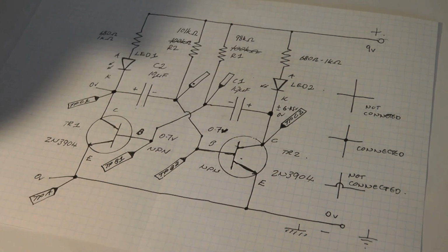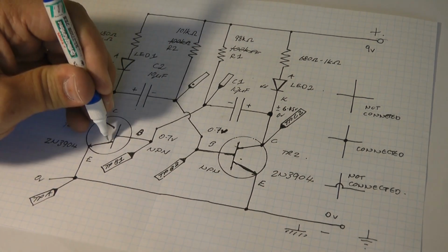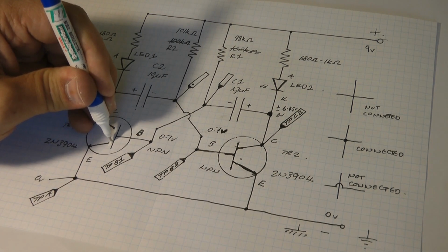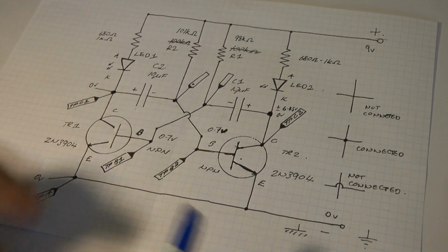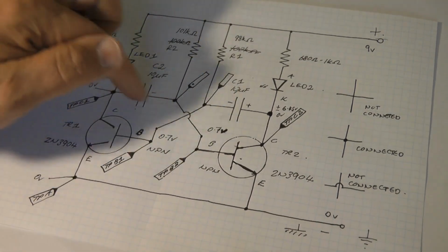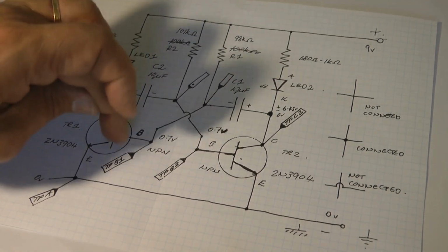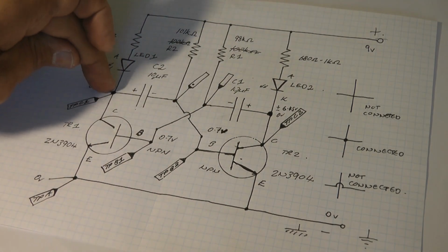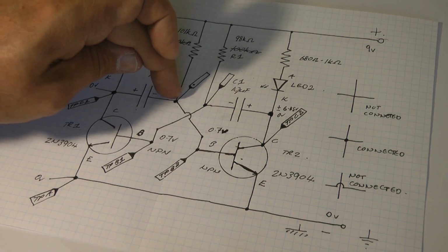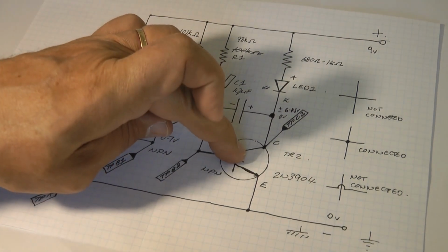So then what would have happened, we'll just do that like this, we would have had an open contact switch on this side again. What you've seen so far is they both came on rather quickly, but this one came on a few instants before the other one, and as this one came on, that went to 0 volts, and that pushed this into deeply negative territory, which would have forced this transistor off.